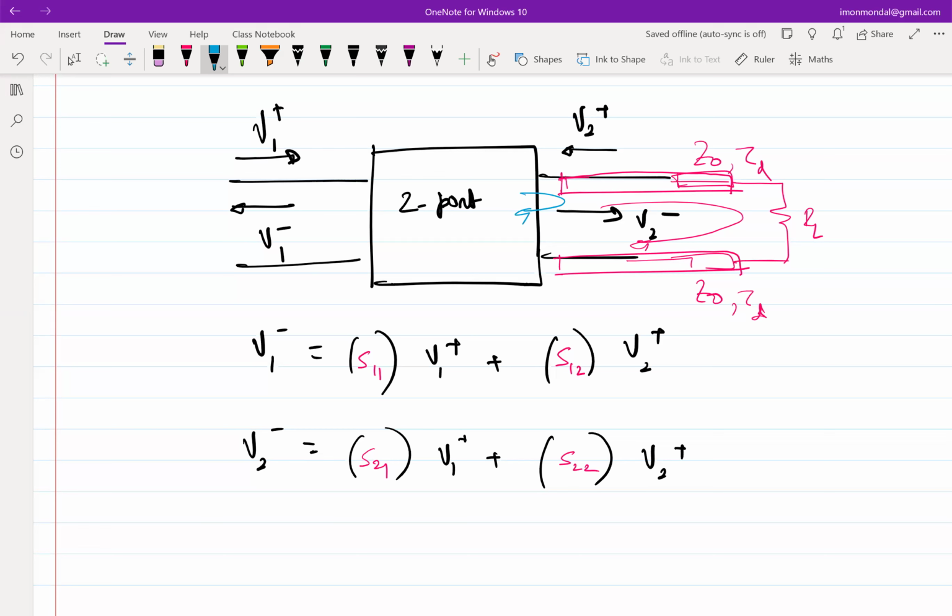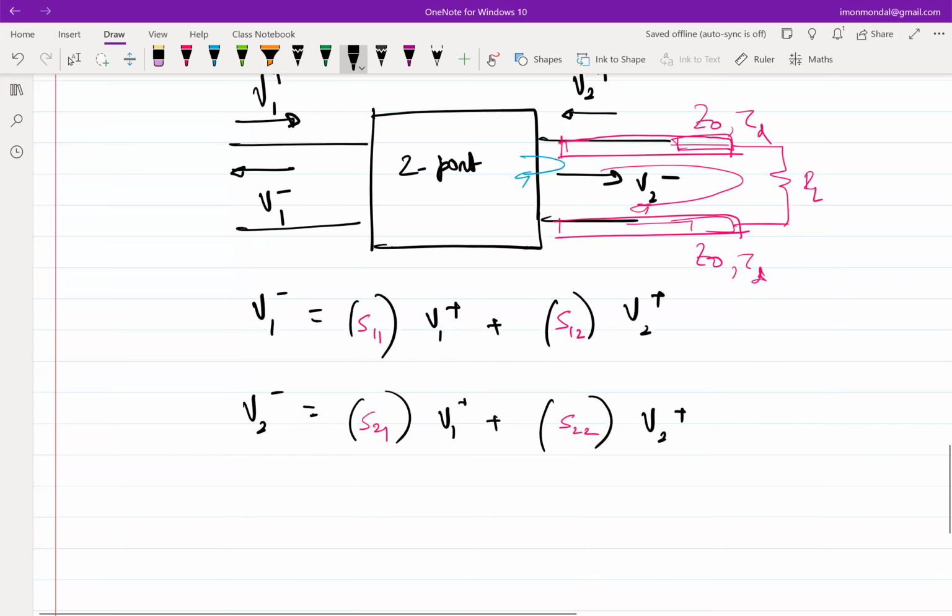Why is that fine? If that length is infinitesimally small with respect to the time period of the waveform, then essentially that is equivalent to saying your load is directly connected there, right? If the load is directly connected there, then it's not a problem. The problem comes because it has to come through a round trip delay. By ensuring that your RL is equal to Z0, you are negating that round trip delay, right? So if you ensure that RL is equal to Z0,